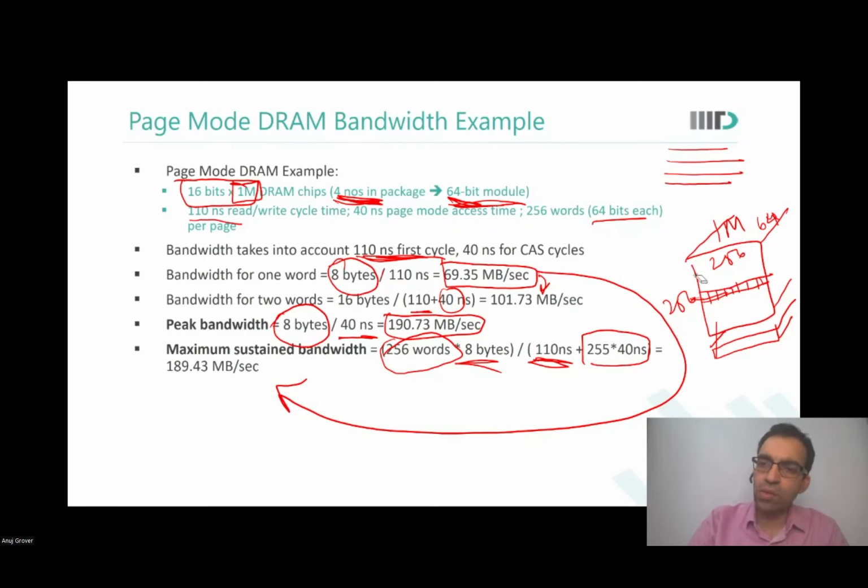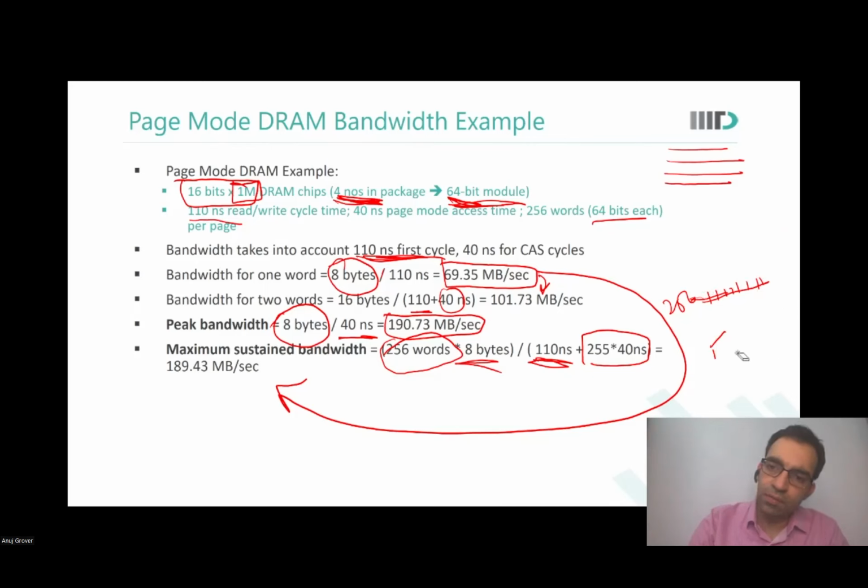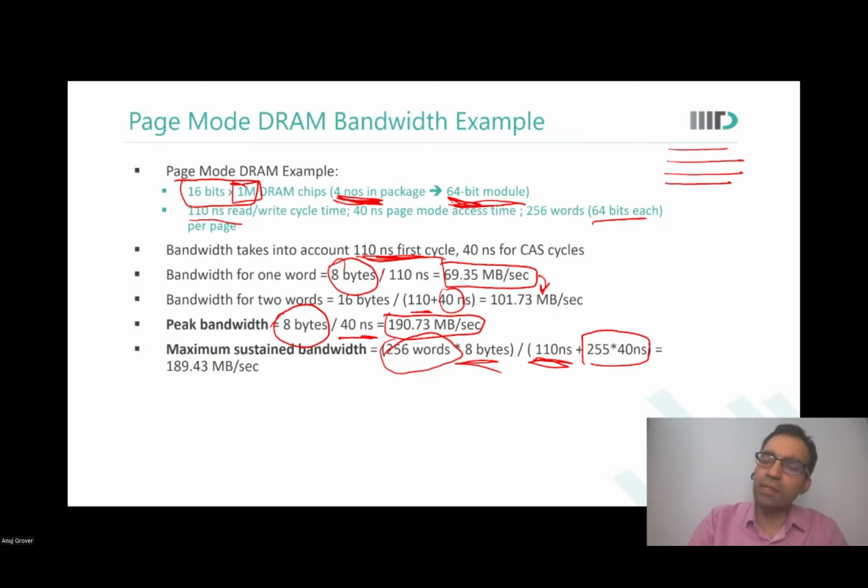So let us go into a little more detail of multi-die packages. We talked about it in DVD, I think. I do not distinctly remember. In multi-die packages, there is a substrate which has all the pins. These are what are soldered onto your PCBs. And multiple dies means that each die would have its pins connecting to different package-level pins.